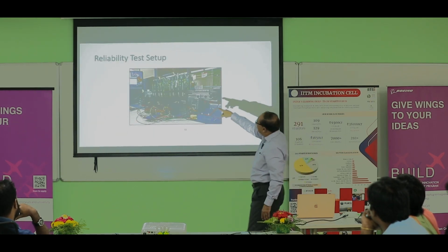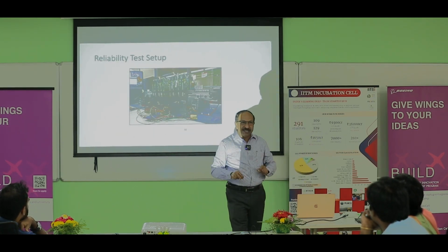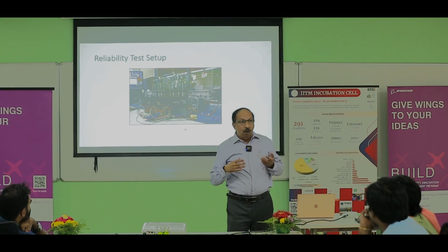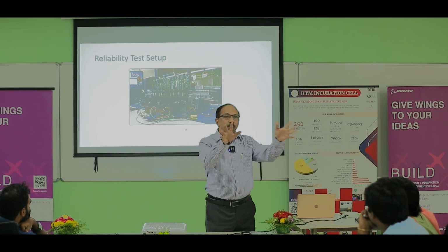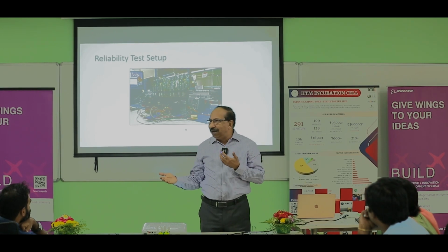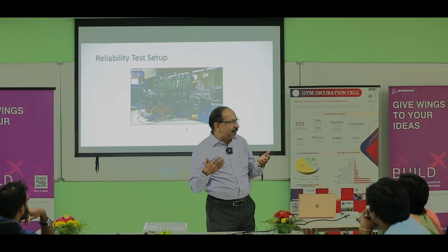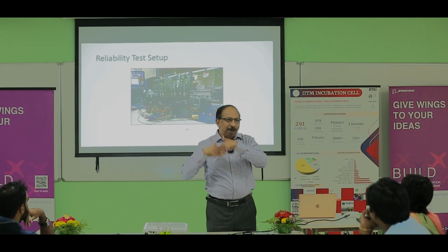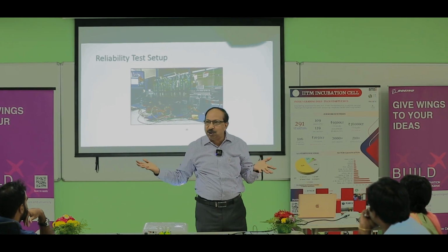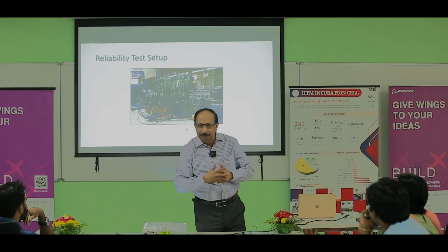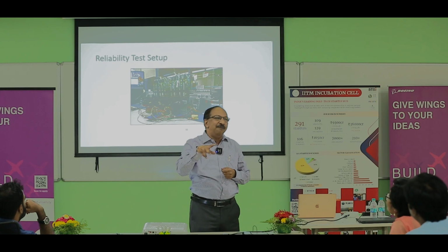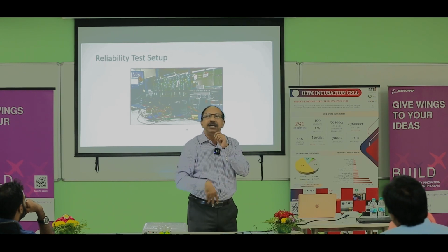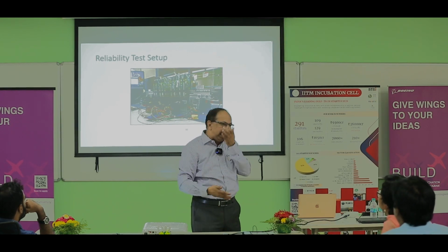One of them I am showing here, there were keys. You have to estimate what will be the number of times this key, for example the power on key, will be used. I will tell, like a doctor will work a day, maybe 100 times he will press, multiply by 10 years it has to work, so 10 million times, something like that. So you have to physically press that switch for 10 million times and make sure that it still works. Okay, then only you can tell that this will work.